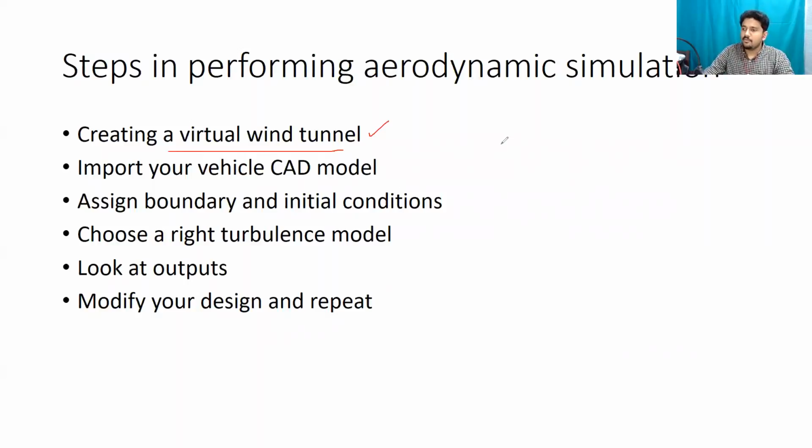So when you take experimental setups, how do they determine the aerodynamic performance of your car? What they do is they take your car and put it inside a really large room, and on one end of the room there's a fan that blows air at a particular condition. This is what you call a wind tunnel. You can set up force sensors or pressure sensors on the car, and estimate the amount of force acting on the car, in other words, the amount of force that's preventing the car from moving forward. This force would be the drag force.